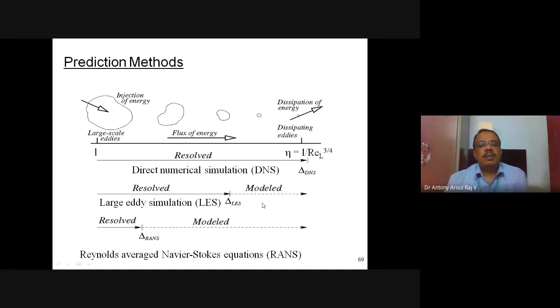But even for smaller problems where turbulence is not important, for example in an air conditioning problem, the shape and formation of the turbulence is not important. Why? If I am taking a chimney problem or a cloud problem, there the large eddy structure formation and dissipation is very important. But for our case, it is not important. It is enough if we know the effect of turbulence in the flow field, how the flow profile and the flow velocity are altered. That is what we are interested in. So that is why we are going for modeling. The type of modeling we are doing is called RANS modeling.